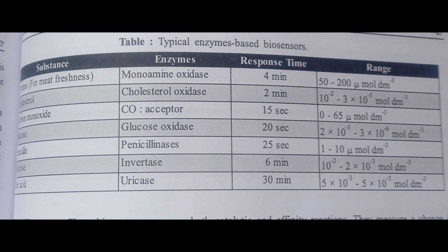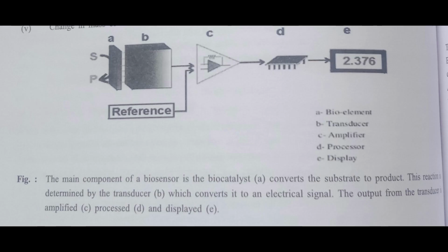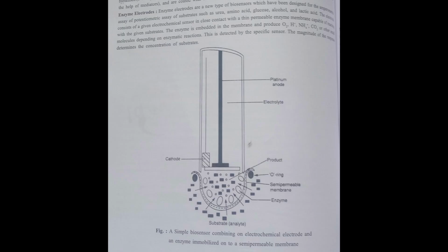7. Acoustic wave biosensors. These are also called piezoelectric devices. Their surface is usually coated with antibodies which bind to the complementary antigens present in the sample solution. This leads to increased mass, which reduces their vibratory frequencies. This change is used to determine the amount of the antigen present in the sample solution.